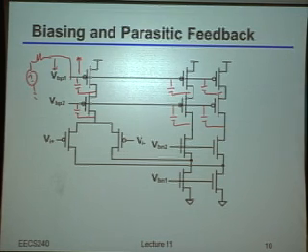So again, let's say that gate goes high. What's that going to do to the tail node of the input pair? Which direction is that going to move? Is it going to move up or move down? Again, the gate of a PMOS transistor, which is the current source, went up. Yeah, so it's going to go down, right? It's a common source amplifier. This tail node here is going to go down.